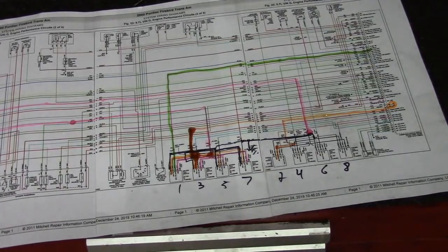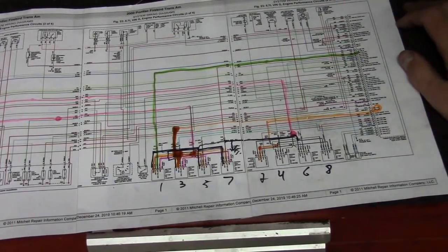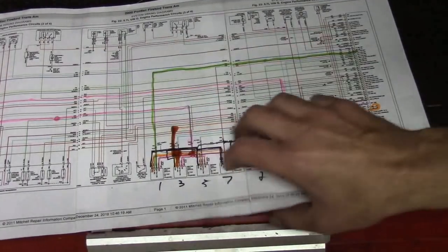So if we saw one of those signals on that parade that we didn't like, we would have some ways that we could identify which coil it was coming from. And we'll get there in the future. That's a little more advanced. It's pretty easy to do on this car, though, because we can measure it by current through the common ground.